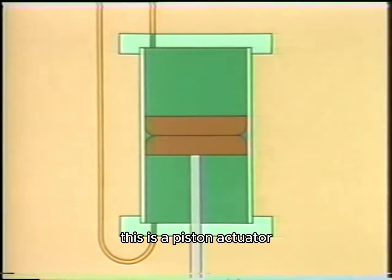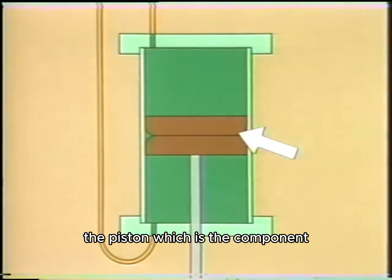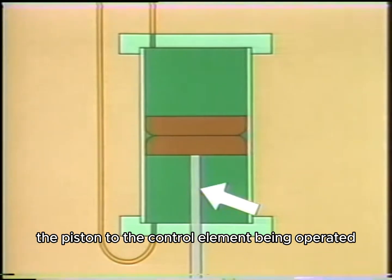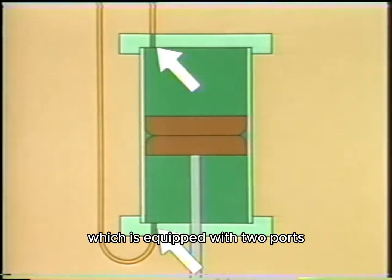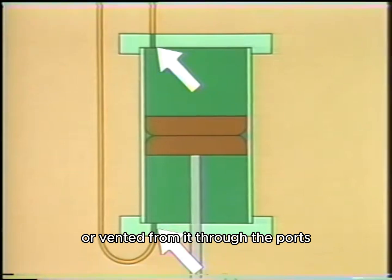This is a piston actuator. It gets its name from its primary moving part, the piston, which is the component directly acted upon by air pressure. A piston rod connects the piston to the control element being operated. The piston rides inside a cylinder, which is equipped with two ports. Air pressure is supplied to the cylinder or vented from it through the ports.